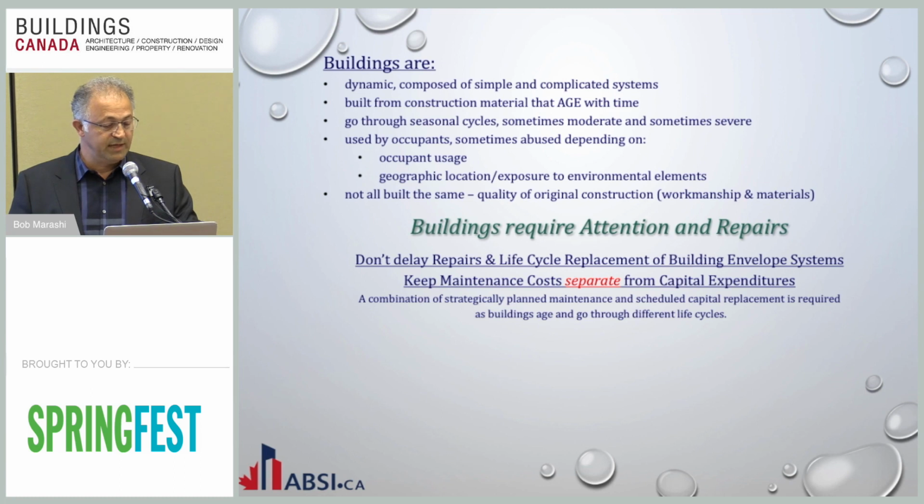A word of advice is don't delay any repairs or life cycle replacement of building envelope systems. Keep the maintenance costs separate from your capital expenditure. Don't think that because you repaired a few things in your building, now you don't have to carry out that expensive capital expenditure in 2 years. You still need to do that. Keep them separate. A combination of strategically planned maintenance and a scheduled capital replacement is very important as your building goes through its life and ages and goes through its life cycle.